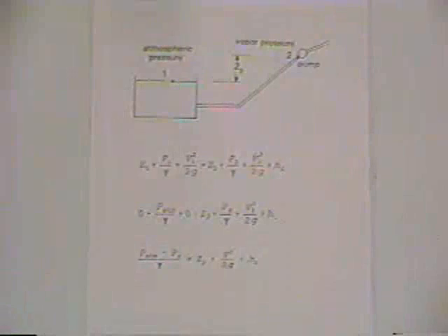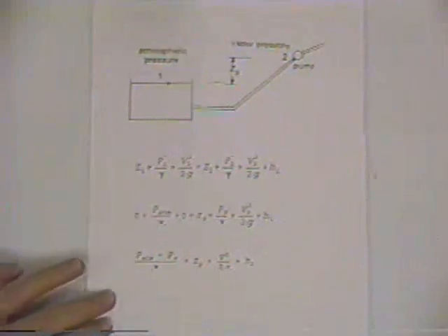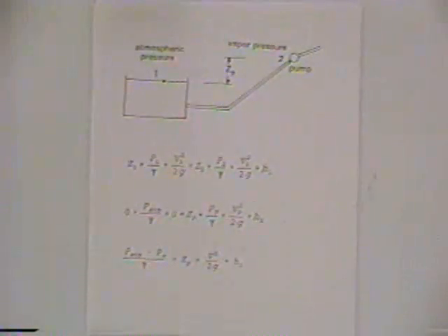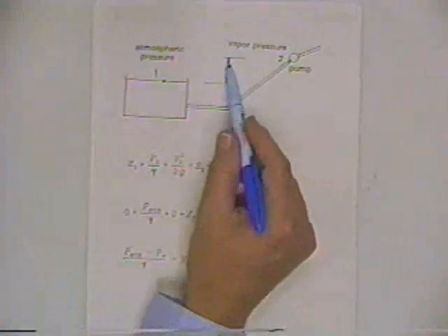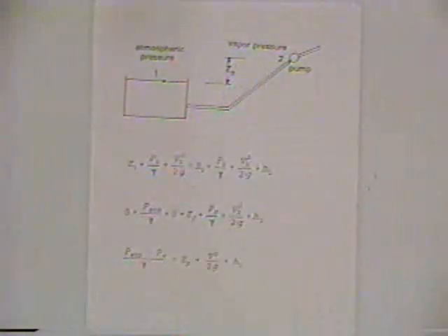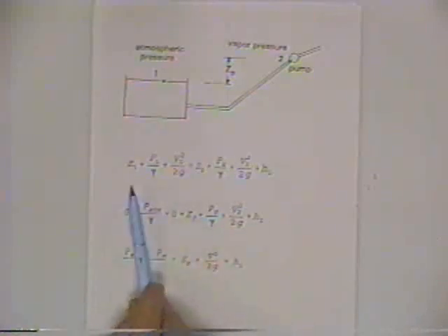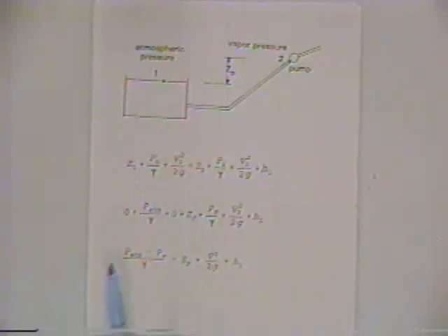We did it that time with numbers, but this is a classic problem of fluid mechanics that gets worked a lot, and basically it's just in this format. The pump is some distance above the water surface, Z sub P, and in another problem you could be solving for Z sub P, given that you know Q. If you look at the energy equation, it's going to look like this, and you're going to be plugging in the atmospheric pressure.